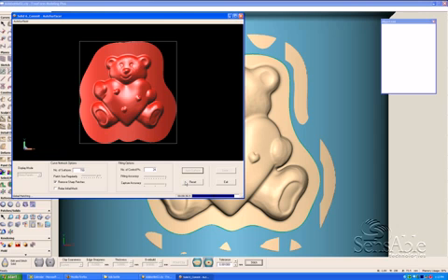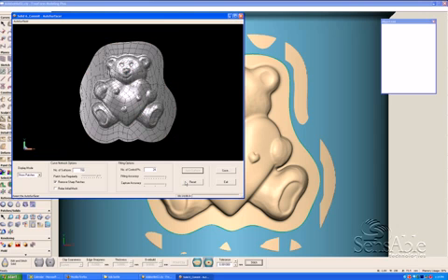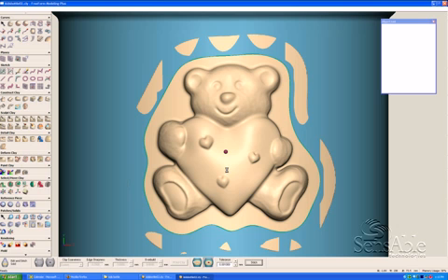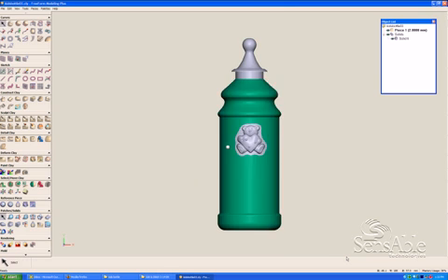So what I'm doing right now is surfacing this model in the Auto Surfacer, and I've selected a number of surfaces with a number of control points, and those can all be changed to get the Auto Surfacer to surface the way you'd like. And then when I hit save, it's going to import this surface model back into Freeform, and it's going to automatically trim it based on the curved trim line that I created at the very beginning of this demo.